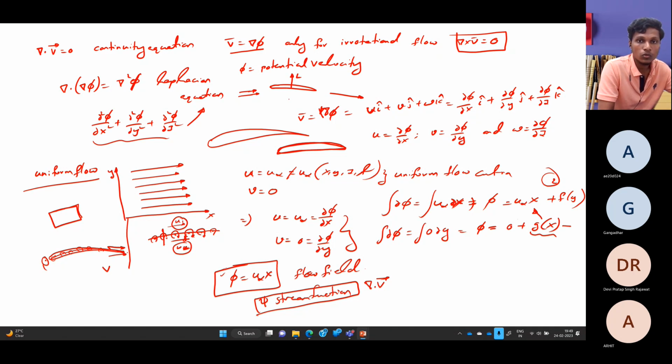Okay, so if you are saying that because of this turning there is a presence of lift force, and in the Kutta condition, if you are not applying either of the two conditions, like the velocity at the trailing edge from the top surface and bottom surface should be equal, V1 should equal V2, or both should equal 0. Either the velocity here is 0, or the velocities should be equal. If neither applies, there should be a presence of a stagnation point.